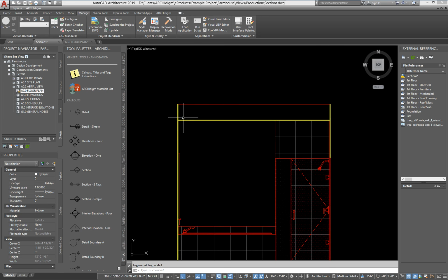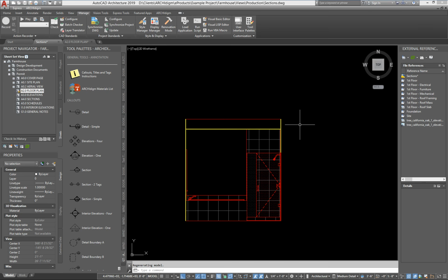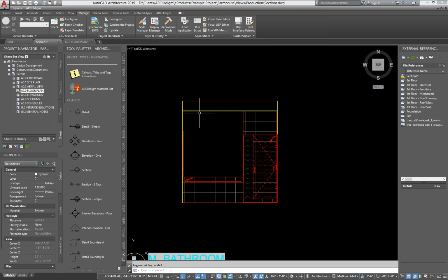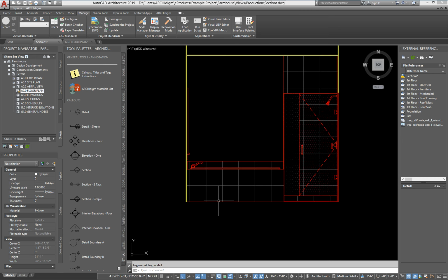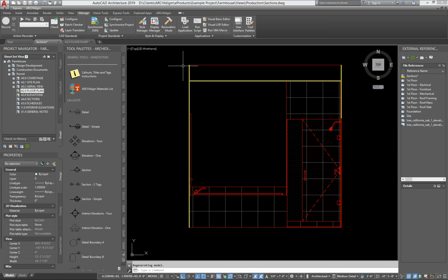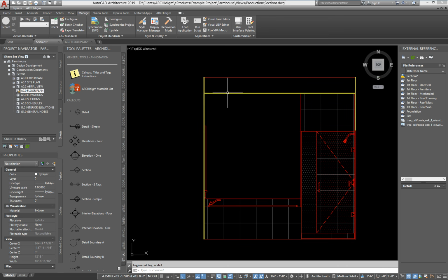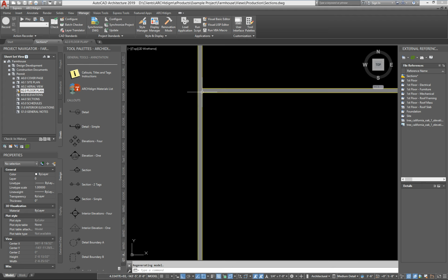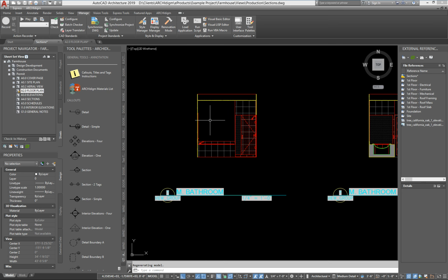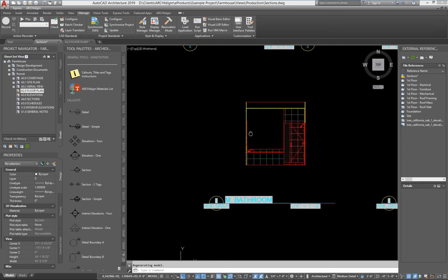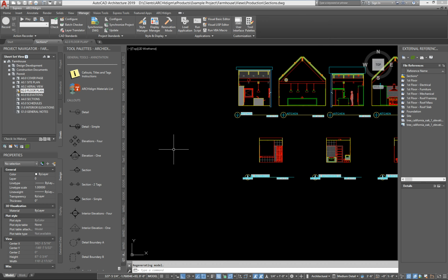And I do. I don't like the ceiling height. It goes up beyond the ceiling, which is not accurate for interior elevation. And I'd like to have the floor. What I do like is I'm seeing that ½ inch. So this is going to print extra dark because of that ½ inch. So if you wanted to emulate the style that I'm using here, you could reduce it to a 1/16 of an inch past the wall, something like that, to get a thinner line. But let's go and fix the top and the bottom range needs some adjustment.